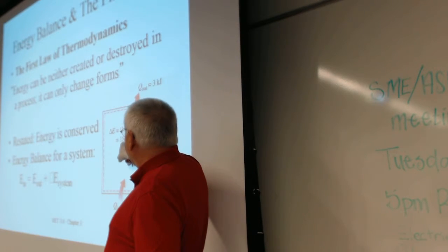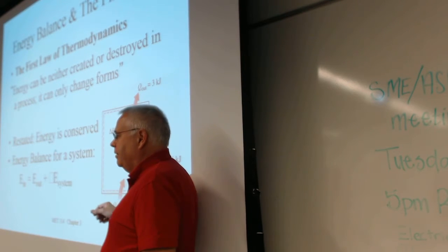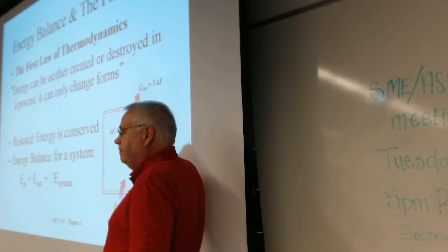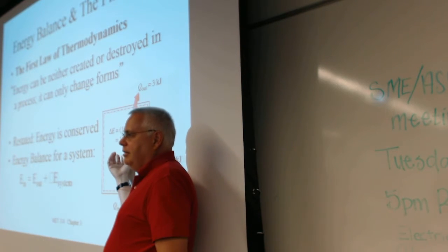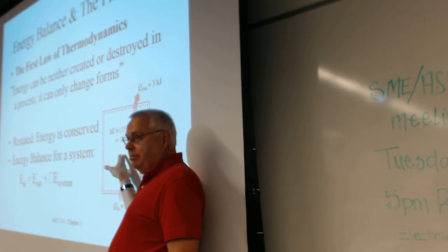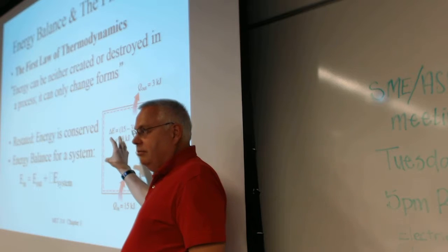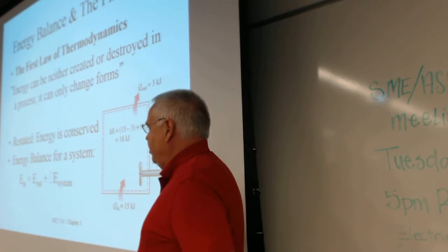We can predict that the internal energy increased by the difference between what went in and what came out. If we knew how much mass that was and what the material was with the Cp, with this much energy, we could predict how much the temperature went up inside. But it's all just the temperature is telling us how much energy there is there.